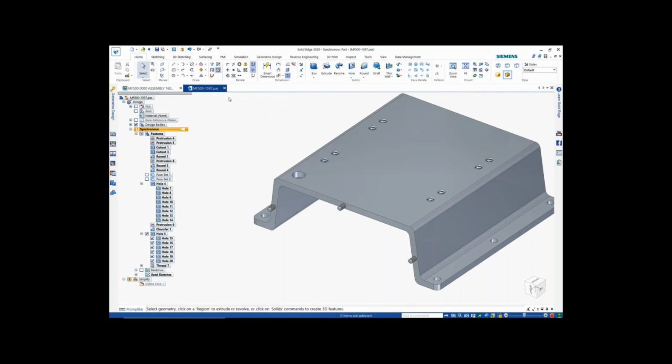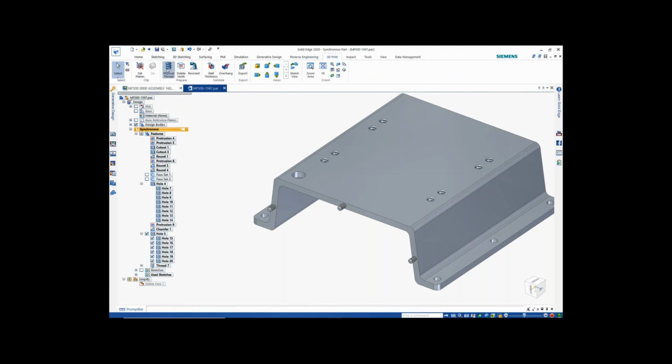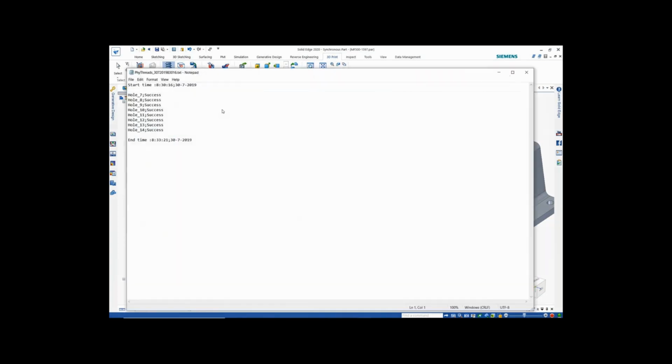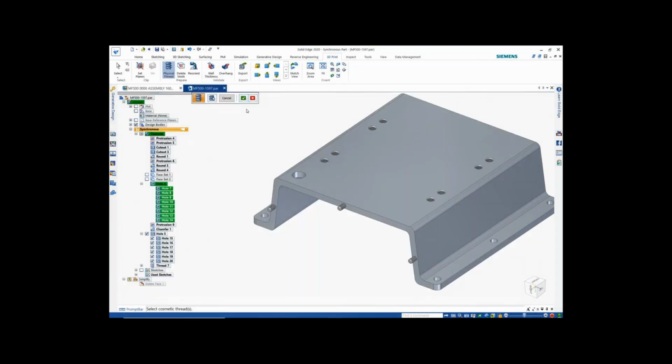I think this is something I would probably do at the end of the design process, just before we send it to 3D print. So I've added this really nice command that will do it globally. You don't have to go and find every hole and click every hole. The software is just going to go find all your fasteners. It knows the thread data. Produces a nice report at the end, just so you know if there were any issues, I can't imagine what one would be. We pretty much know everything about a threaded hole. And then they're all model threads.